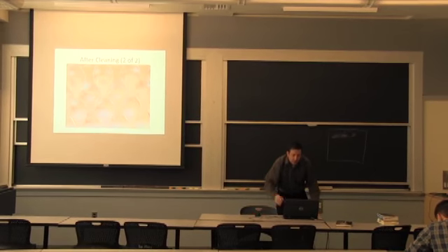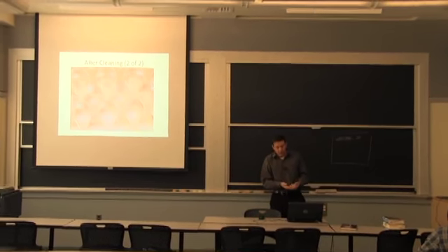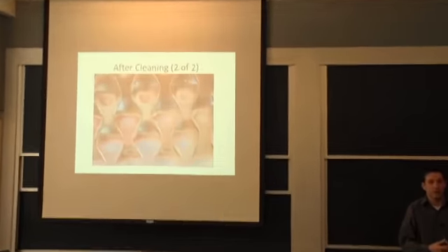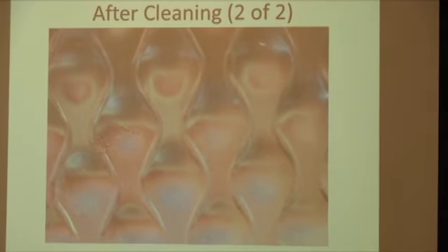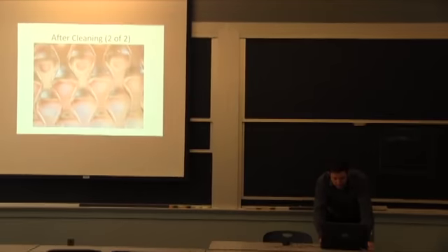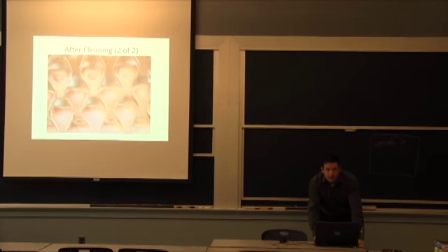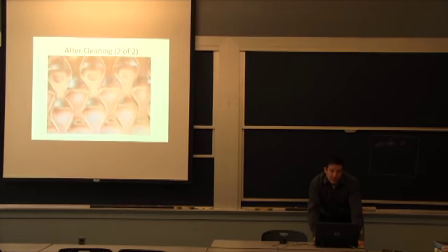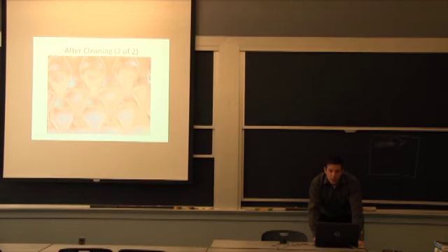So it goes under the effect that we talked about of pitting corrosion, where you create a local environment, all of a sudden you're not passivated, and you're going to penetrate through the stainless steel very quickly. So if this was a pressure vessel, a thin wall pressure vessel, we would be worried about that as well. And I've seen that in vessels used for water treatment plants. They use free chloride. They have all sorts of cleaning solutions that can be aggressive enough to create a problem of pitting of the stainless steel.